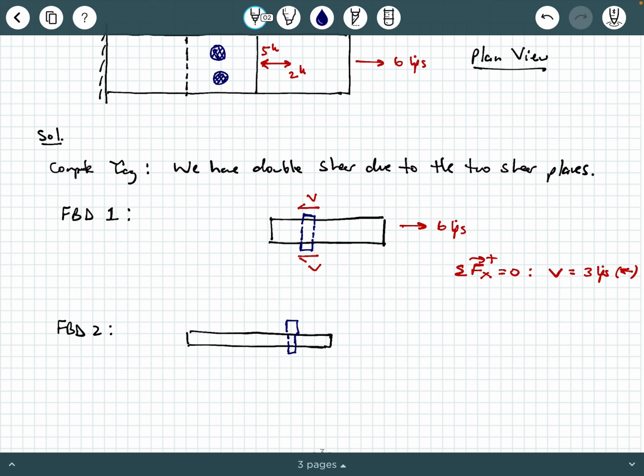There's the nub of that, and applied to the top plate, we had that 5 kips from the problem statement. Now, what's happening at the interface of this bolt, right at the interface of the plate where the nub of the bolt is? Well, we're going to have 3 kips right here, pointing to the right.